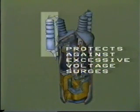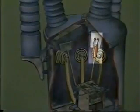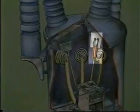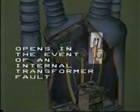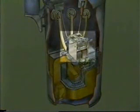The arrester, as you know, protects the transformer against excessive voltage surges. This internal fuse, which is placed in series with the high voltage winding, is designed to open in the event of an internal transformer fault. And this circuit breaker is located in the low voltage winding.